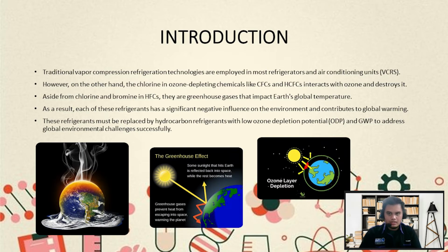First of all, the introduction of the hydrocarbon refrigerant. The traditional vapor compression refrigeration system (VCRS) technology is employed in most refrigerators and air conditioning units. However, the chlorine in ozone-depleting chemicals like CFC and HCFC interacts with ozone and destroys it.